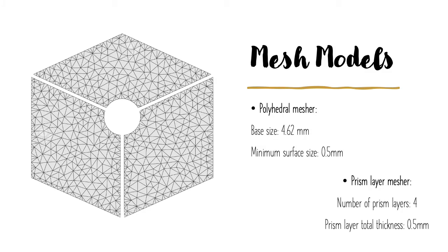After creating the CAD on Inventor, it is important to establish the mesh models. Firstly, polyhedral meshes. As the pump has a complicated geometry, a polyhedral mesh is required to maximize the curved zones. This unstructured mesh has a better simulation if the number of vertices increases. Also, the polyhedral mesh leads to a quicker convergence of the numerical solution.